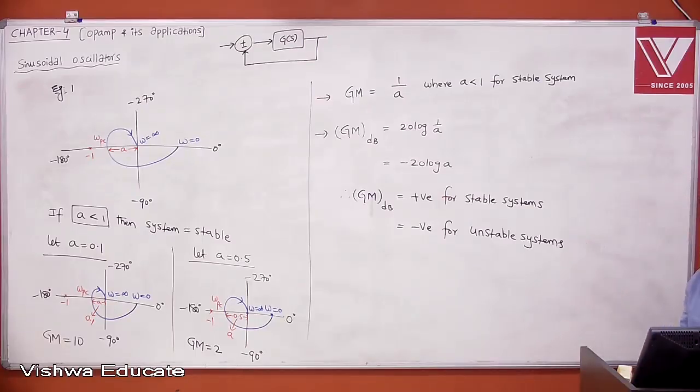In that case, practically people consider the practical variation of k or DC gain, across PVT: process variations from the fab, voltage due to power supply, and temperature due to ambient conditions or power dissipation from your IC. Remember, K is varying, such that if the gain is less than 1 at the phase crossover frequency, the system is stable, even though it has 3, 4 or 5 poles.